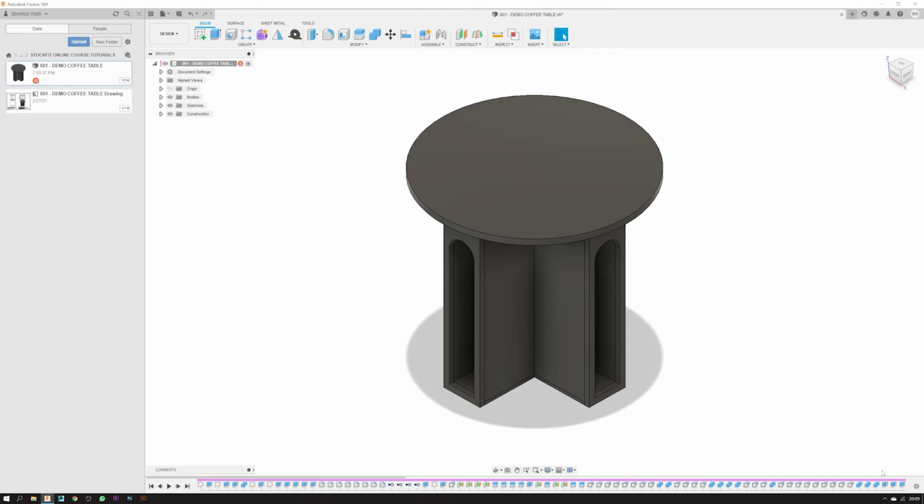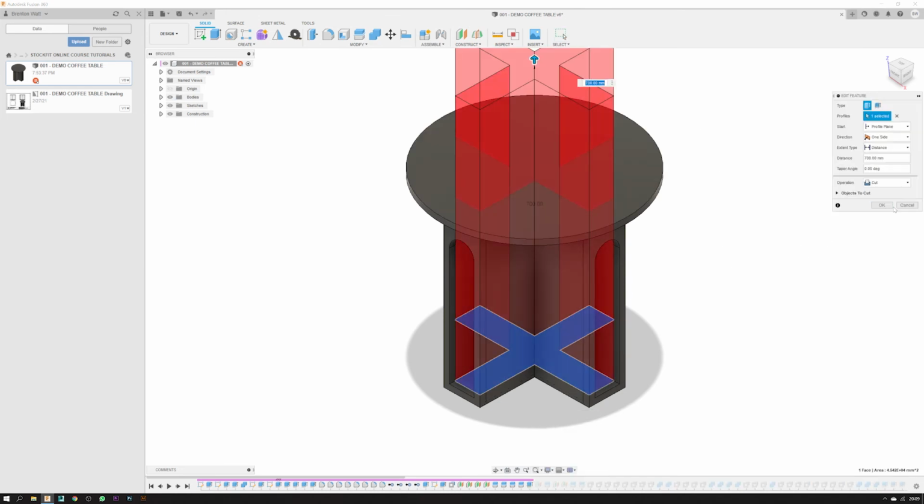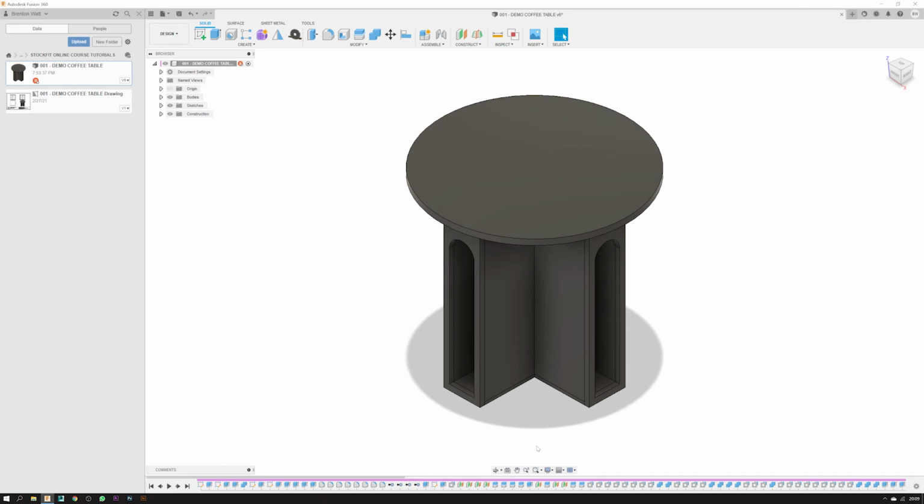You could always, at any point, jump back to an extrusion point or whatever history point that you created, and then you can right click on it and either delete it or edit that feature, and basically you can tweak and change whatever you want. So if you've spent the last hour designing something and you realize, oops, I made a mistake 15 or 20 or 25 minutes ago, you can always jump back in your timeline, go and fix it quickly, jump forward in your timeline, and off you go. So this is a wonderful thing.